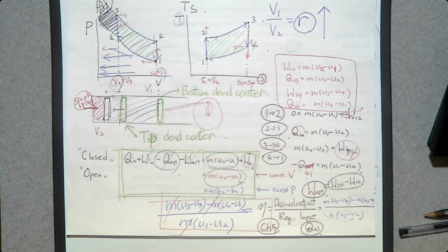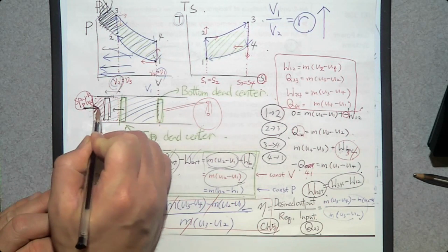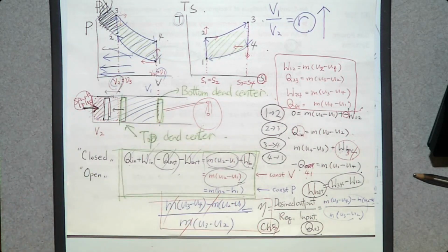Then, can we do that all the time? Not necessarily. The problem is here, the spark plug. What this one does, it ignites the air-fuel mixture, right? So if you compress too much, then before this one ignites the air-fuel mixture, due to high pressure and high temperature, it's going to self-ignite.